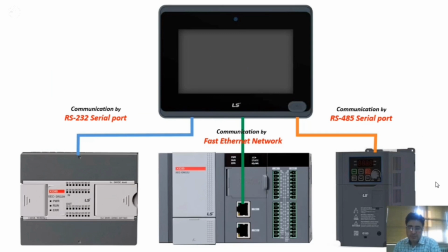Based on these essential ports that I have just thoroughly introduced to you, we can effectively connect each and every one of these distinct ports to a specific device. For example, we can conveniently connect an HMI, which is a human-machine interface, to a PLC, a programmable logic controller, via the reliable RS232 serial port. Alternatively, we can simultaneously establish a connection to another PLC through the versatile Ethernet port, and additionally, we can also utilize the robust RS485 port for further connectivity options.